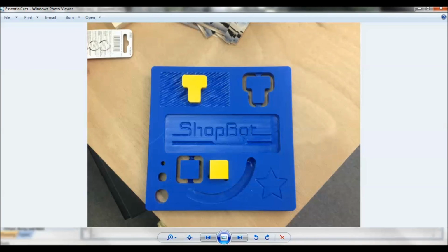This was an inlay, or you can do a male and a female. It's another toolpath. Here's a profile on the line for the star. Notice the profiles don't have to go all the way through. I didn't want that star pocketed out. I just wanted the vector of the line. Here's a pocket where this is pocketed out, and then there's a V-carve down inside. That's where they have the start depth.